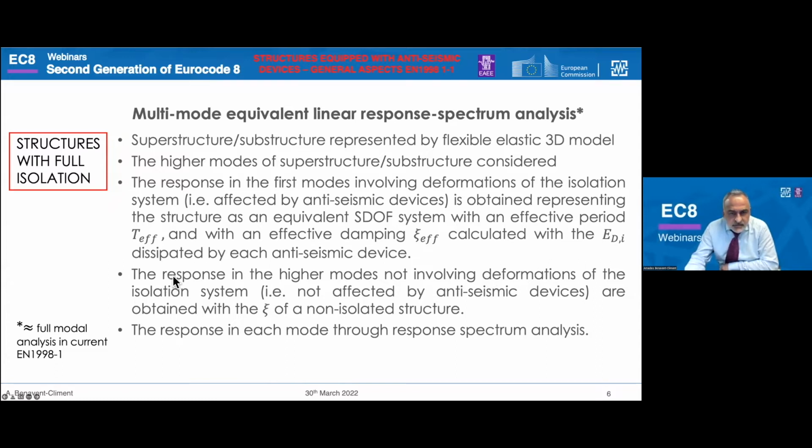As for the response in the higher modes that do not involve deformations in the isolation system, the response must be obtained using the damping ratio of a non-isolated structure. And the response in each mode is obtained as usual through the response spectrum analysis.